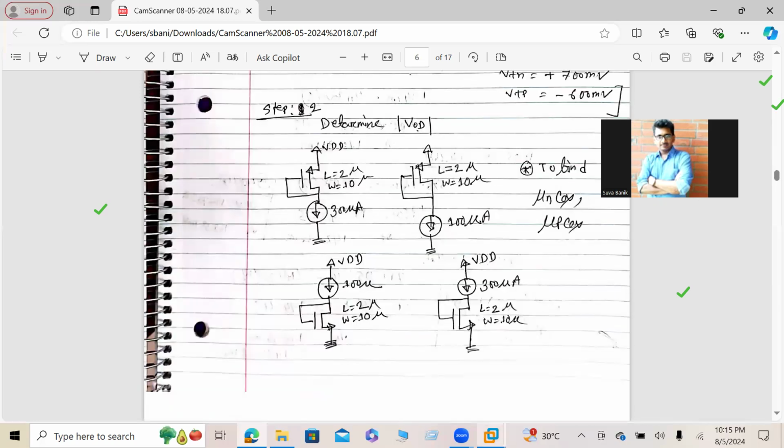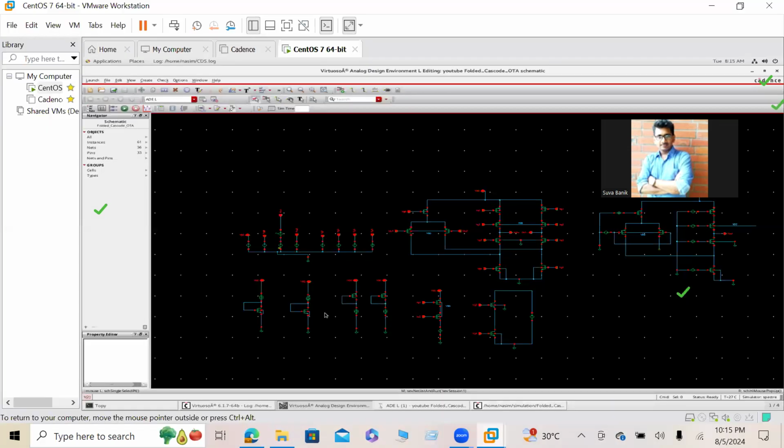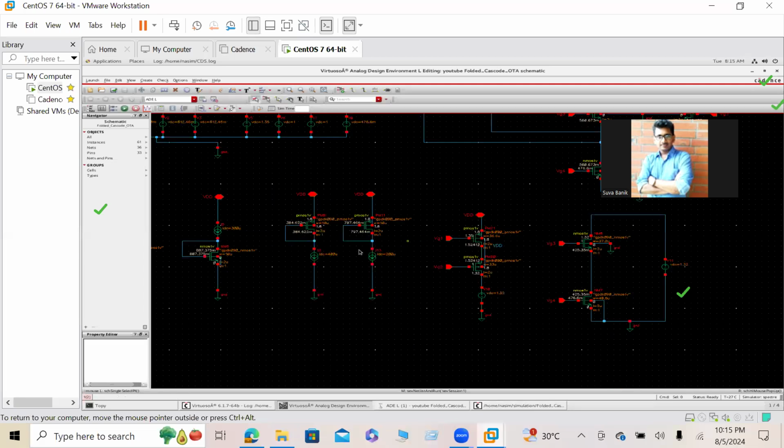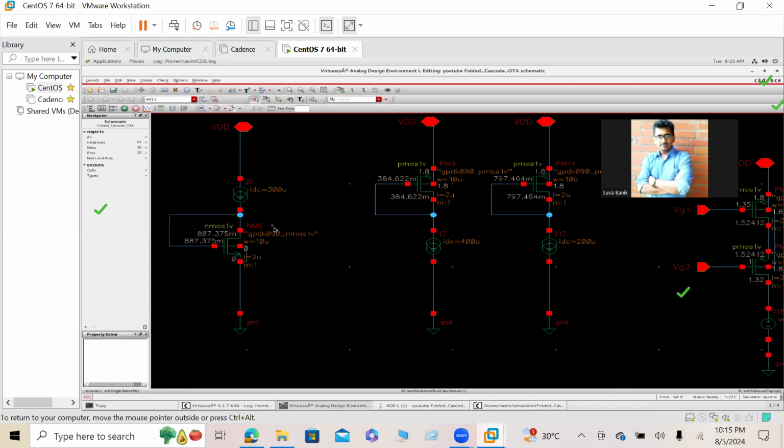And we can also see this from DC analysis. If you make a circuit like this for PMOS or for NMOS in diode connected configuration, you can pick a current. Here I choose 300 microampere current. I will explain later why I pick 300 microampere. Then you run a DC simulation, and from the DC simulation you find the mu p, the threshold voltage, the transconductance, everything. I already explained this in lecture number 4, so please go there.